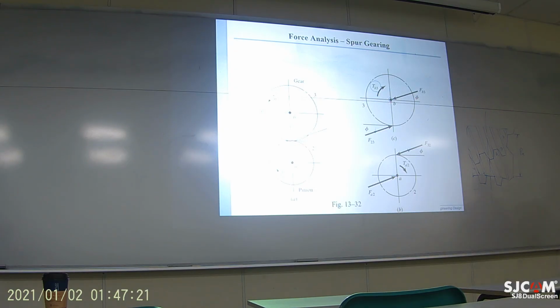Actually, when you have a gear, the mating and operation of the gear and pinion will not only apply a force to the teeth, but also generate a torque to the gear set. So that torque will be applied to the shaft.